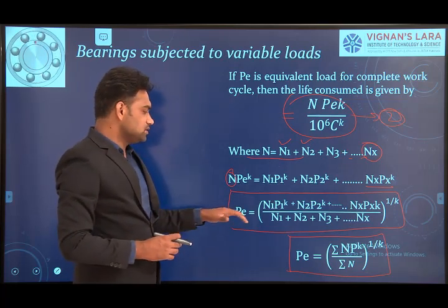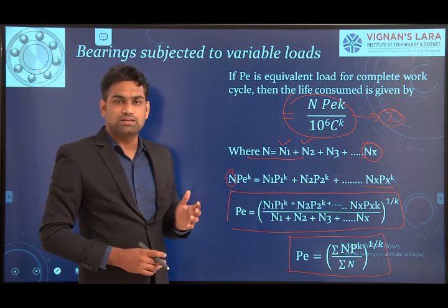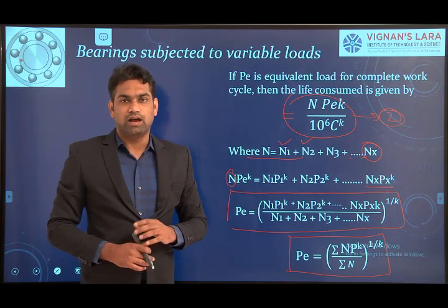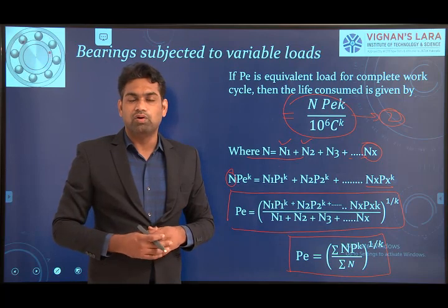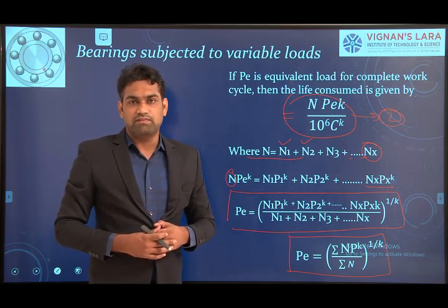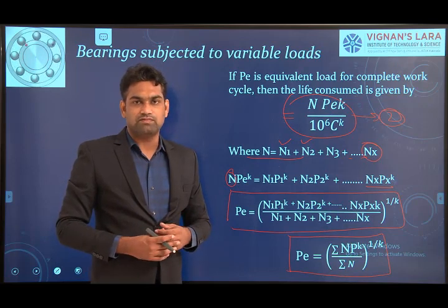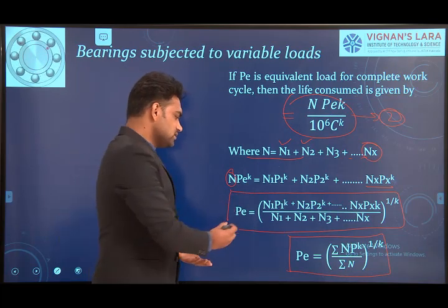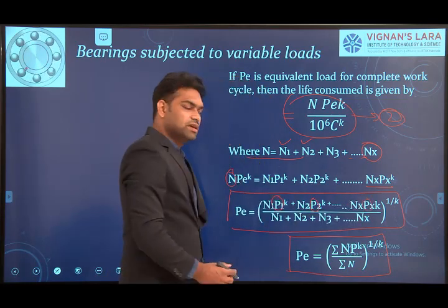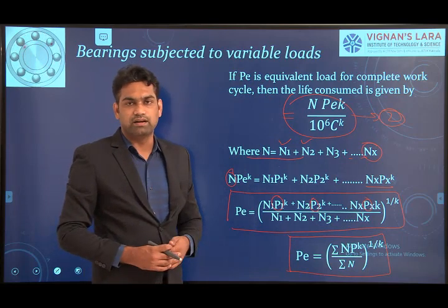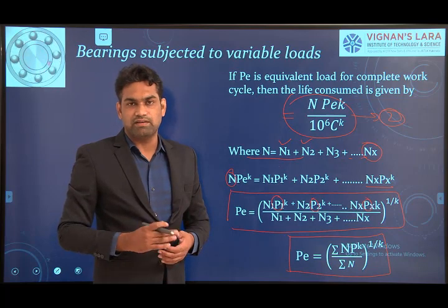Clear? In this equation, as we discussed in the earlier sessions on selection of the bearing under static load conditions, the equivalent load P can be calculated using XVFR plus YFA into S, where S is the service load. In a similar way, the equivalent loads P1, P2 up to Px can be calculated using the same standard equivalent dynamic load equation, XVFR plus YFA.